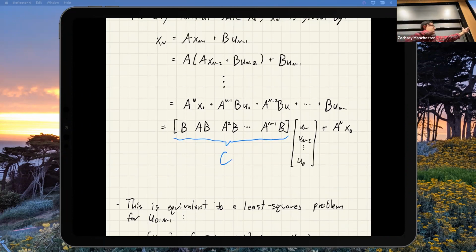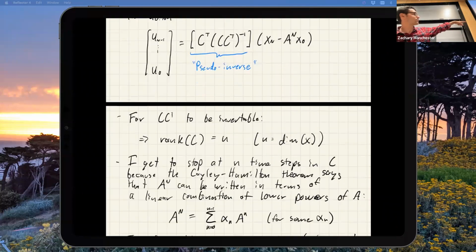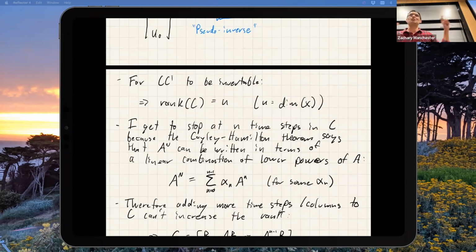So if I have a time varying problem that's finite horizon, like a trajectory tracking problem, then I can ask the question, can I drive the error to 0 at the end of that finite horizon? And I can write that down exactly like this. Those A's in there will have subscripts, but this still works. So this result still holds, but the one down here with only little n time steps breaks in the time varying case. Does that make sense?